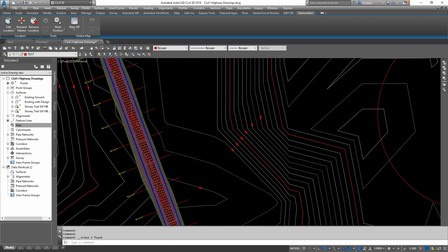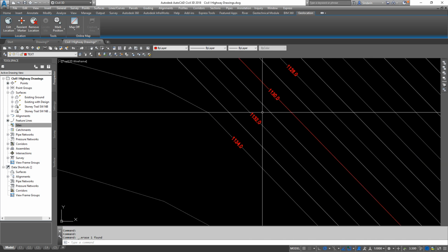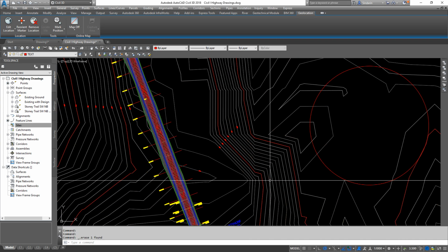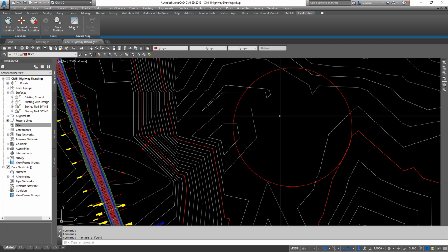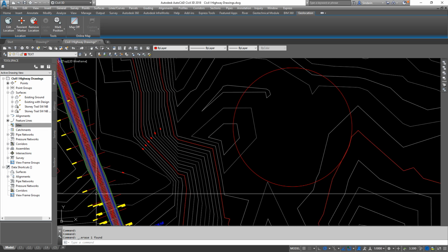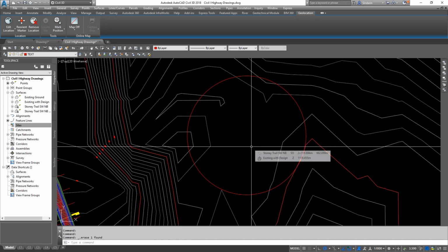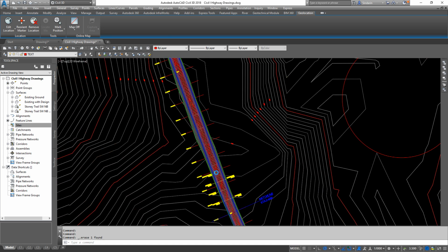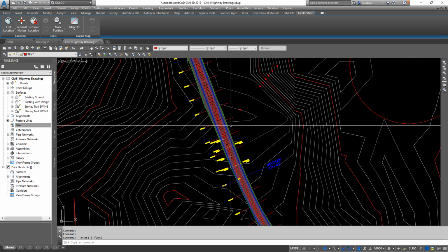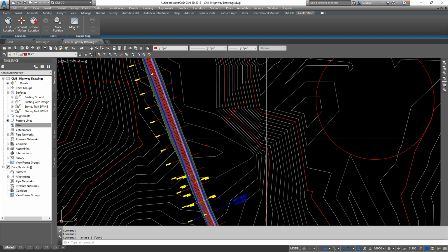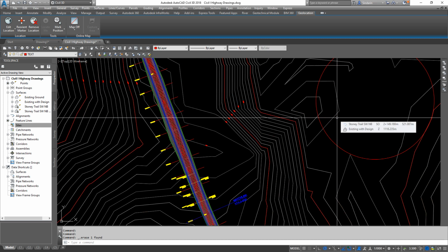So I'm going to build the pond down here, and just looking at the contours, if we go 1134, 1132, 1130, this water all flows downhill, which helps us out. So water can come off our road, down the hill, into the pond. In this case, we don't really need to worry about a high water level. We'll probably just place it at existing ground and build our berms up. But in real life, you will need to figure out the elevations of your ditch over here. You have to design a new ditch from the ditch to the pond at maybe 0.5%, maybe 1% slope.